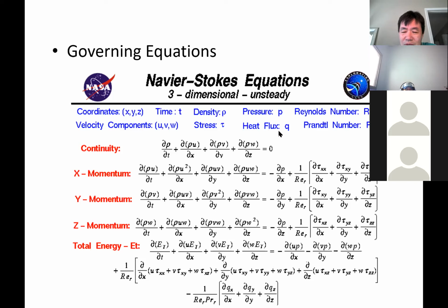So that should be fine. Everything is velocity U, V, W, and the pressure P for the incompressible fluid. Then for the energy form you will have temperature. So these are usually the 5 unknowns you can solve using these equations.